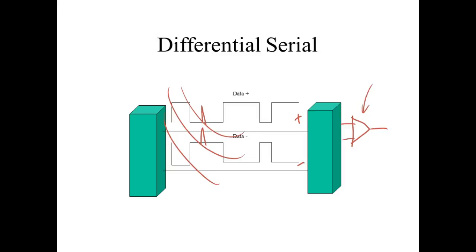And guys, this right here reinvented serial communication. That's why we have Ethernet. That's why we have wired Ethernet. It's not shielded cable. It is unshielded. We call it UTP cable, unshielded twisted pair. We can run that wire 100 meters, 330 feet through just about anything. We just can't carry it outside because of lightning.